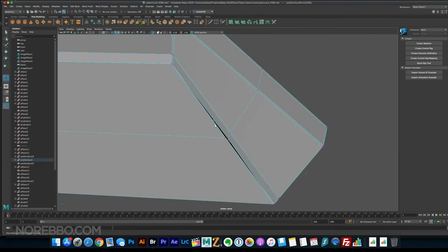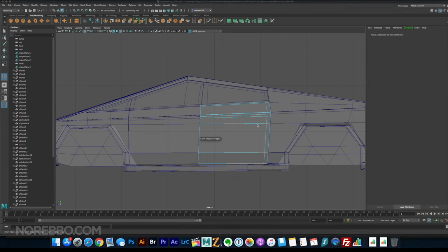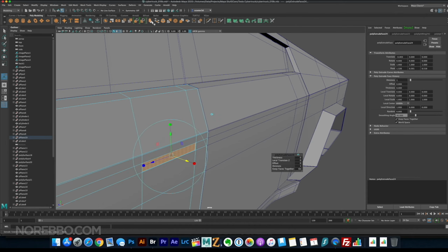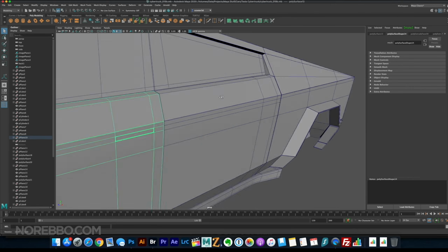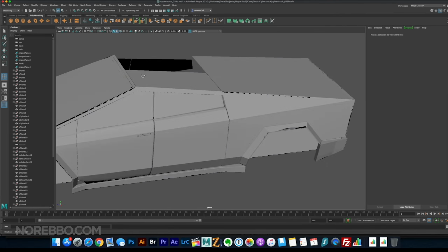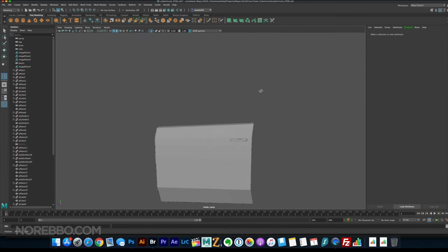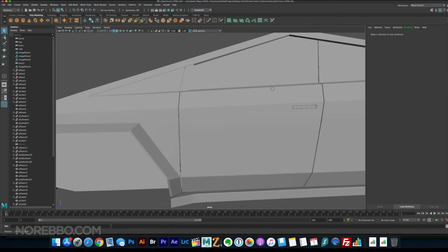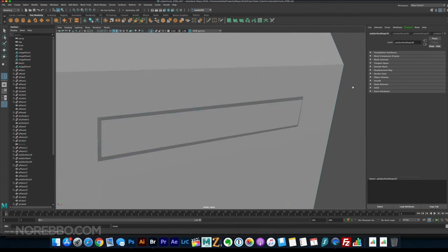Now I'm going back through with the little details. I'm on the front bumper now, and I'm adding edge loops and trying to get that detail there. And this is something I hate doing with automotive 3D models, and that's adding in the door handles. Because normally, especially on cars with very organic shapes, it's hard to cut a section in a door and then not disturb the mesh around it.